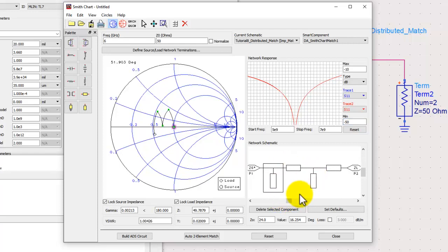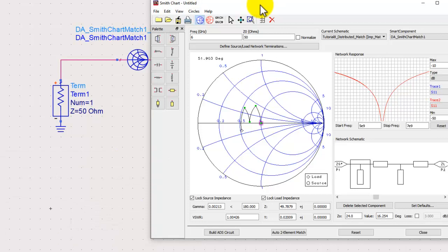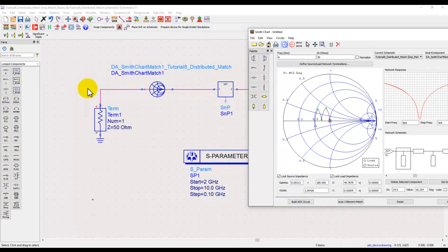But here comes another practical design aspect. Now look at this circuit here. The network which we are trying to design is here. At the input side, if nothing else is connected, let's say I'm only designing this circuit, you will have an SMA connector which will come at the ZS point, or the source point.